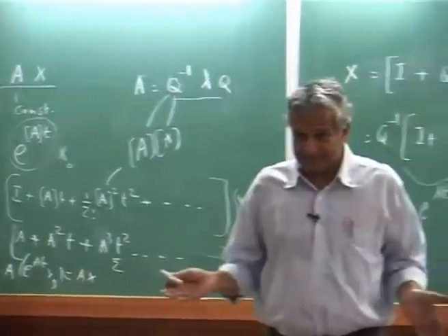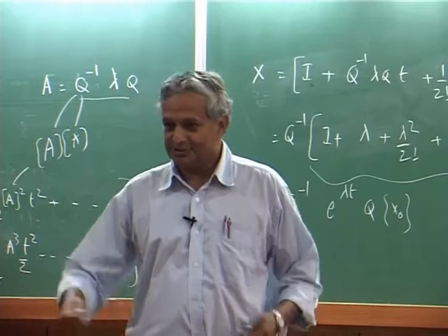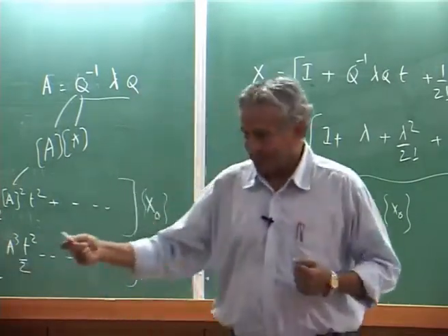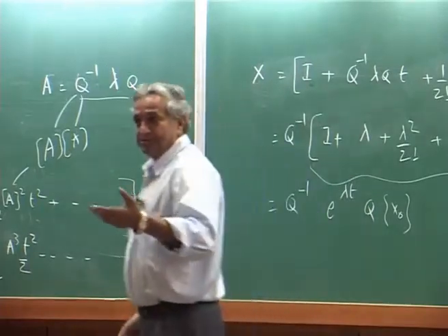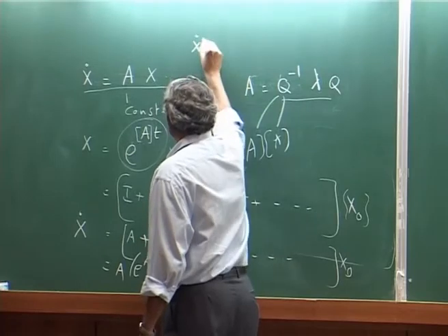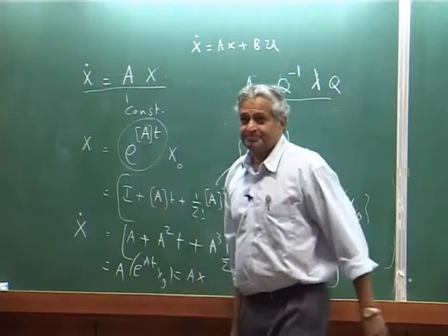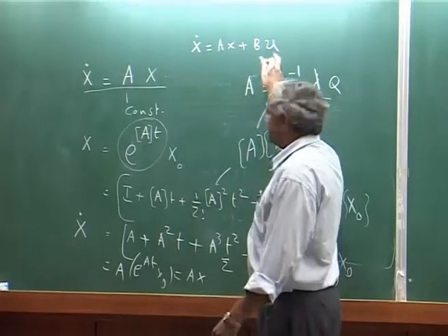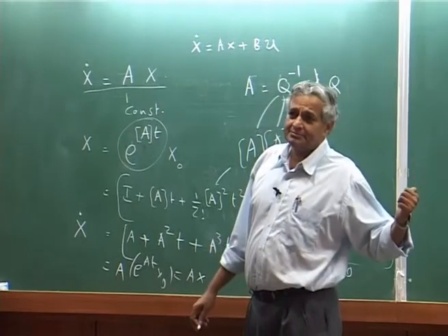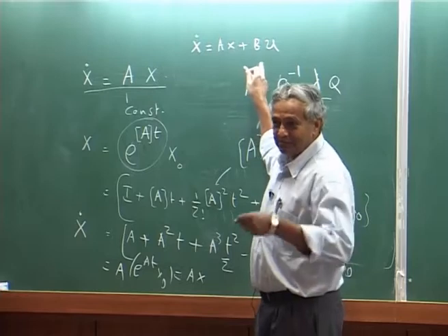Sometimes you cannot make it stable. Okay. Then you start feedback control. This is how the whole subject starts, and then you can have an external loading. Then the control system, they will put x dot equals Ax plus Bu. Now, for helicopters, u is theta naught, theta 1c, theta 1s, theta tail rotor. So, u is the control angle the pilot gives.